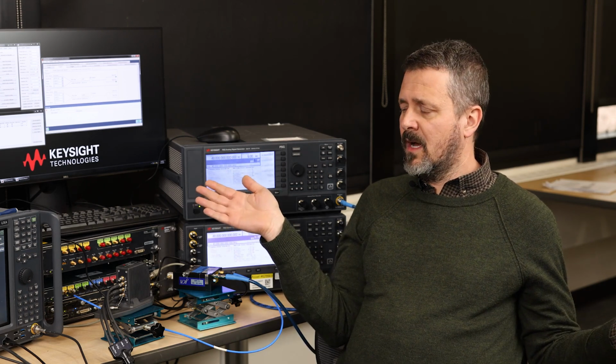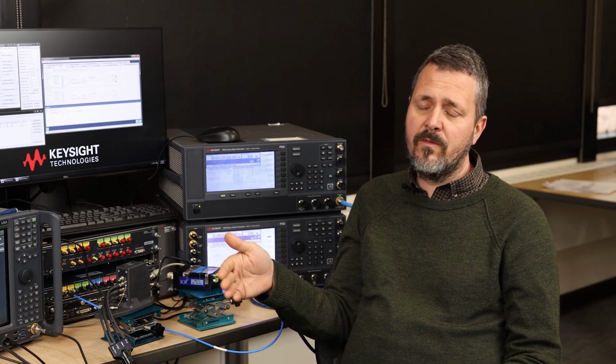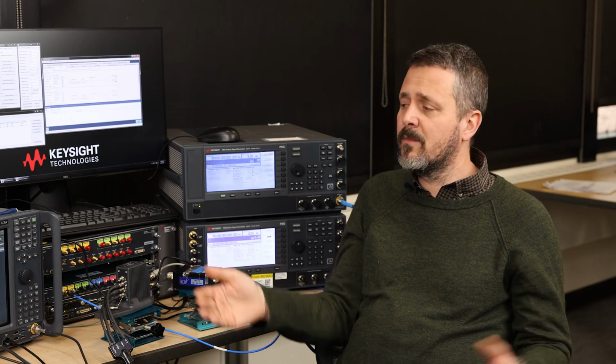So how can I do this measurement faster? Well, one way to make this measurement faster is to use LO gating. So for LO gating, I can use my RF burst trigger to train my periodic trigger. When I'm making really wide span measurements, my RF burst trigger doesn't have the bandwidth to see the signal over greater than 100 megahertz bandwidth. So if I use my periodic trigger, I can train it with the RF burst trigger and set my periodic trigger to trigger reliably every 50 milliseconds, and I could span out.